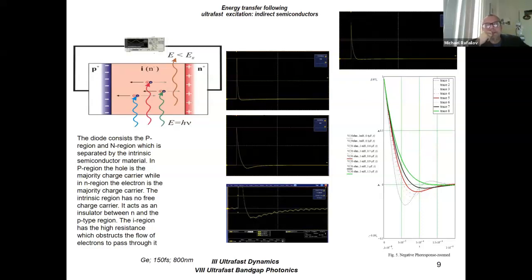In the last chart you see the modulated light. There are no signs of thermal processes, because if we had thermal processes, we should have thermal noise. There is no thermal noise. The temperature pretty much stays the same. So what's the best way to do that? To use a PIN diode, which has a bulk piece of intrinsic semiconductor and doped sides creating the junctions. When these charges come in, they separate and create some kind of current.